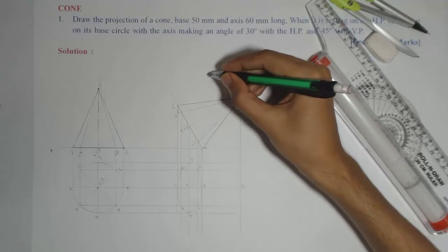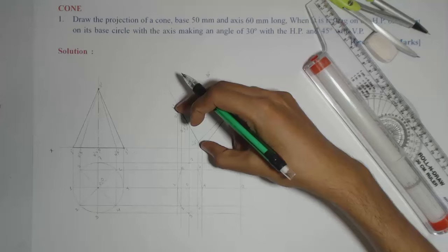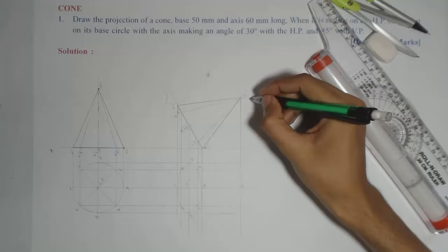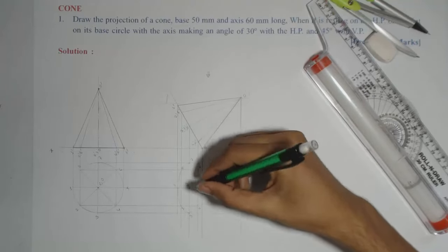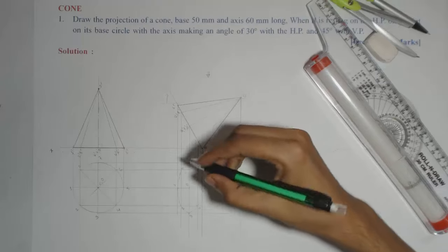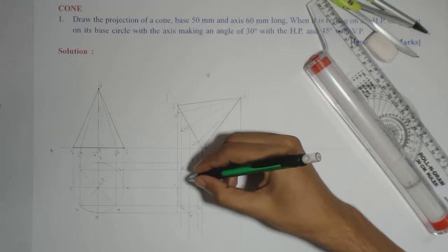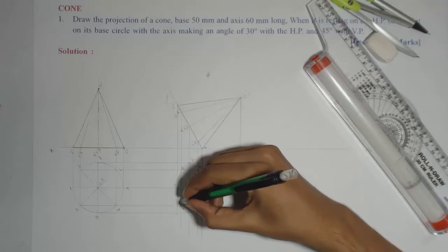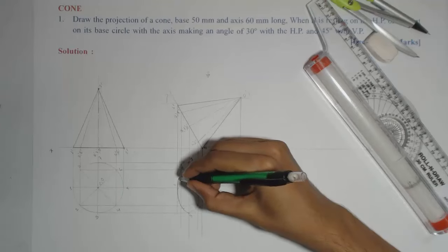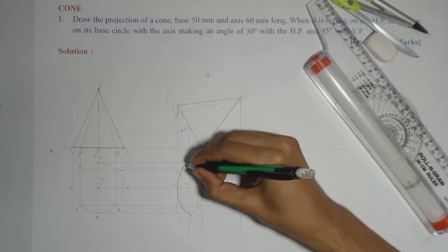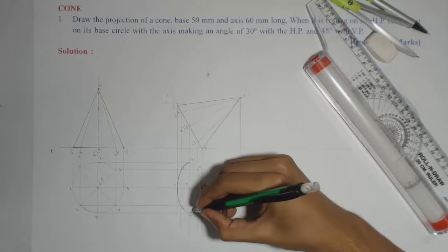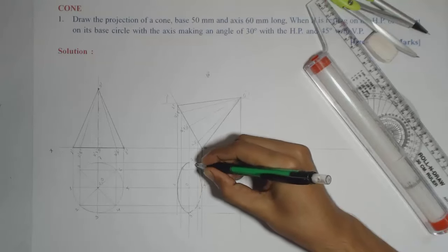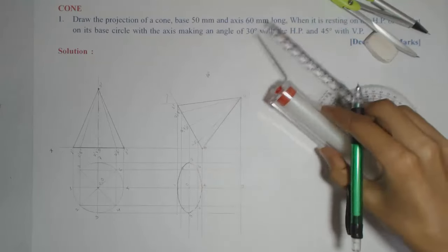Observer will look from this direction. For the observer now the entire base is not visible because only part visible will be above this point and this point. So for the observer the entire base is not visible, but by rules of visibility, if any part is lying on the boundary, then that will be made as dark. So this portion which is lying on the boundary means 3 to 7 will be dark, and the portion inside that which is not on the boundary will be dotted.